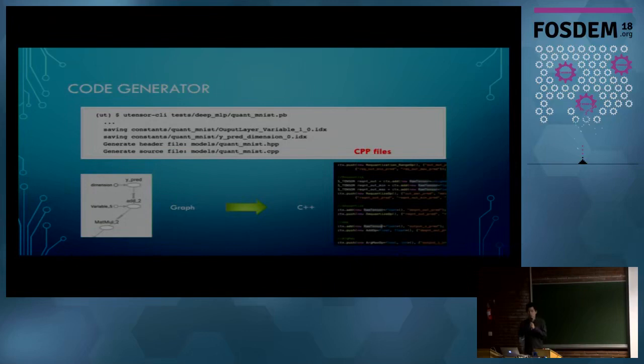And just to reiterate on that one, this is actually the actual command as I was trying to run and make the README file for the project. You will give a graph to the Microtensor CLI, command line interface. And then this little program here extracts the parameters from the graph, which is your weights, and saves them somewhere for you to import onto your device. Also, it generates the C++ file you will need to do inferencing on the microcontroller.